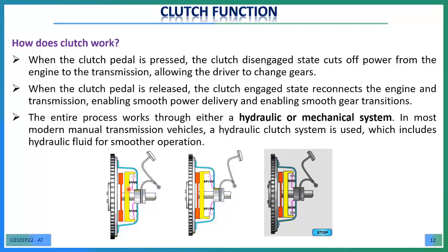Both are separated, so the engine power and the transmission are disconnected, and that is the time the driver can change the gears without affecting the gear system, so smooth transmission takes place during that operation. The second one is when the clutch pedal is released.